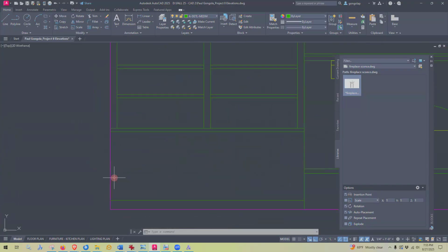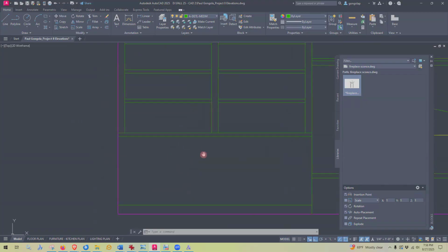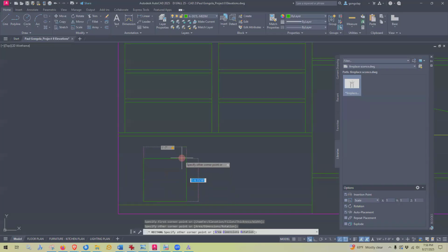All right, let's look at our doors. So I've got some double doors over here, and then I have 2 doors over here for the base cabinets. And the doors are 19 inches wide by 30 inches high. So let's draw our first door. I'm going to use my rectangle tool, and I'm going to go across 19 inches. And I'm going to use tab to lock in the 19 and then switch to the vertical dimension, which is 30.